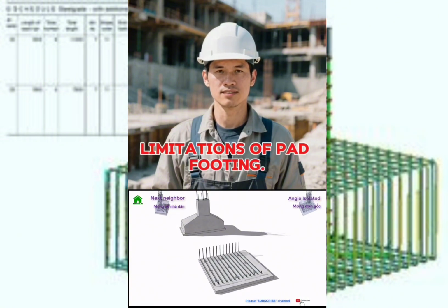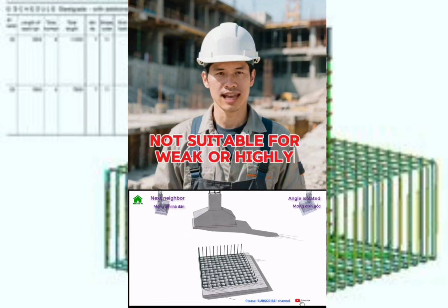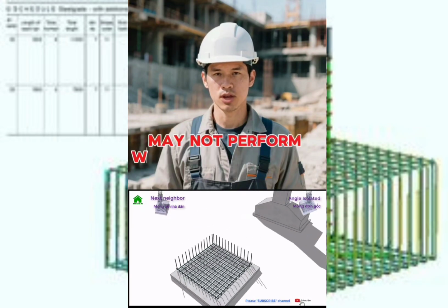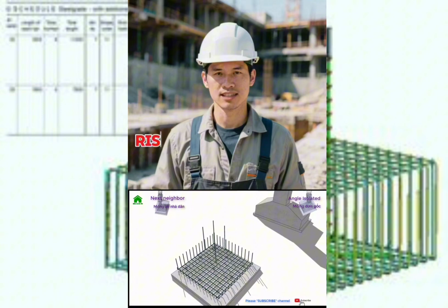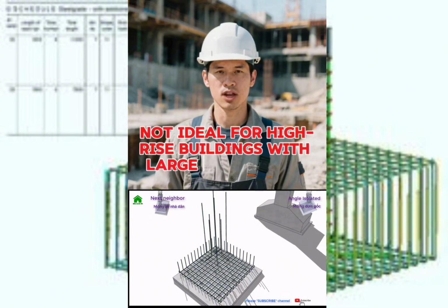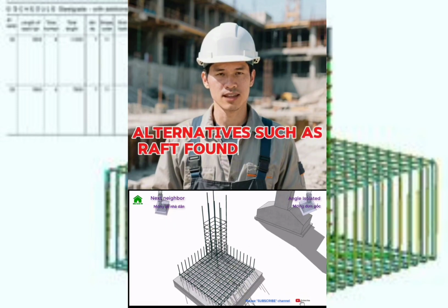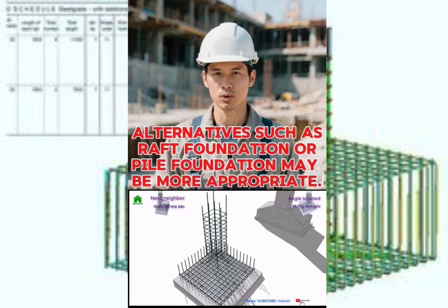Limitations of pad footing. Despite its advantages, pad footing has some limitations. Not suitable for weak or highly compressible soils. May not perform well under heavy or eccentric loads. Risk of differential settlement if soil conditions vary. Not ideal for high-rise buildings with large structural loads. In cases of poor soil conditions, alternatives such as raft foundation or pile foundation may be more appropriate.